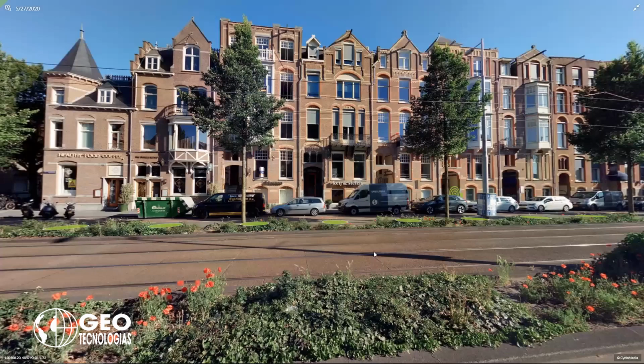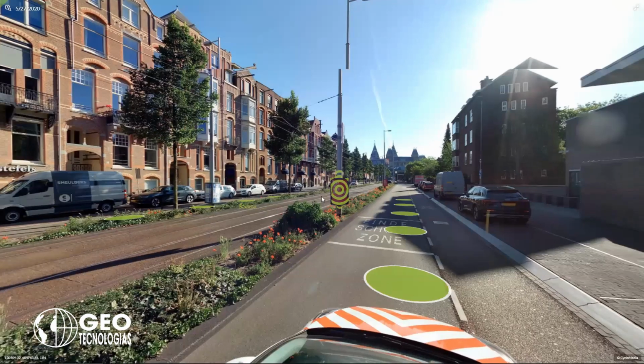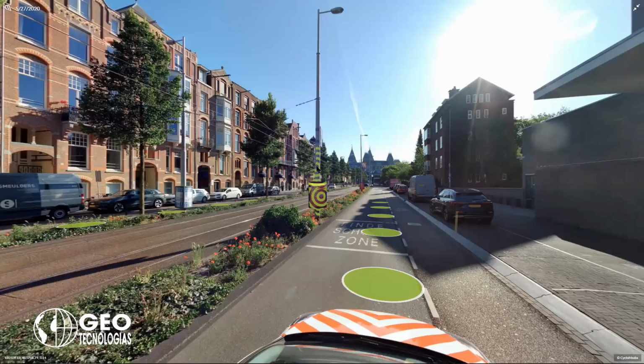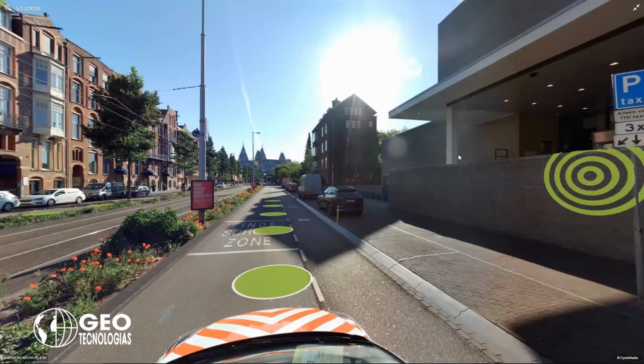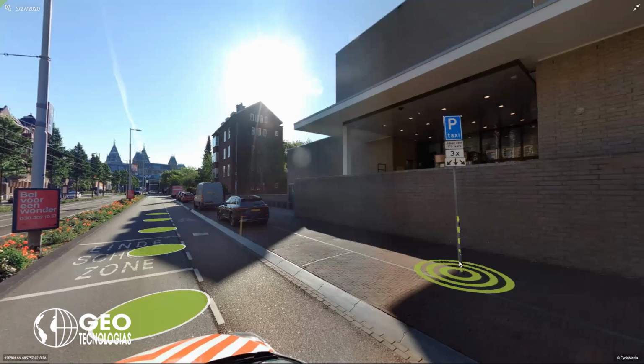As you notice, as I move my cursor around, I'm actually placing the cursor on objects. So with the system, it's actually object aware. And so they're actually performing some photogrammetry in the background where they're generating a digital surface model. And that's how we can move our cursor. And so you can imagine all the different use cases up here, but primarily we have this ability so we can actually collect points within the city, all from this app, and that'll populate our existing GIS.